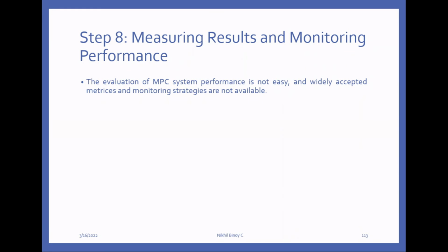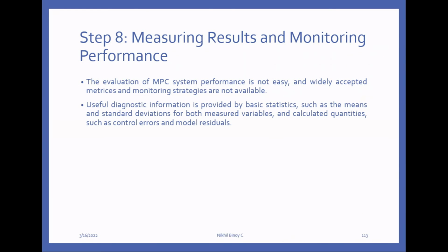The evaluation of MPC system performance is not easy. There are no widely available monitoring strategies. Useful diagnostic information is provided by basic statistics such as the means and standard deviations for both measured variables and calculated quantities such as control errors and model residuals.